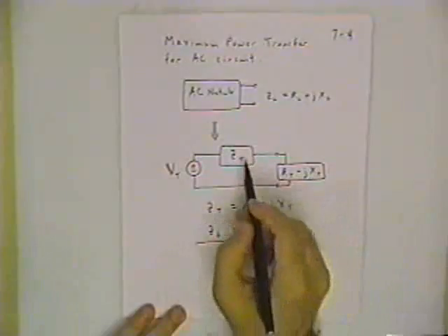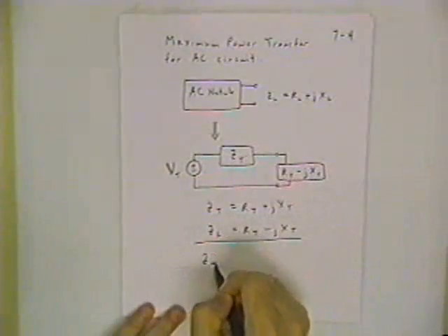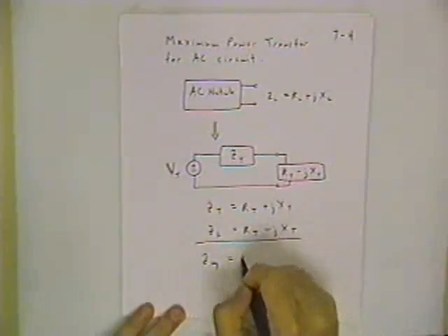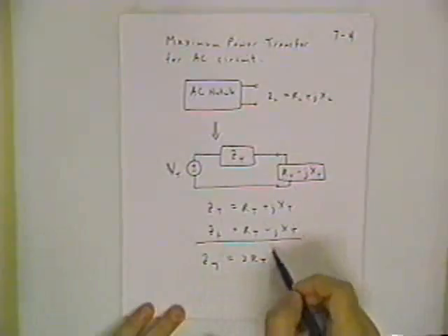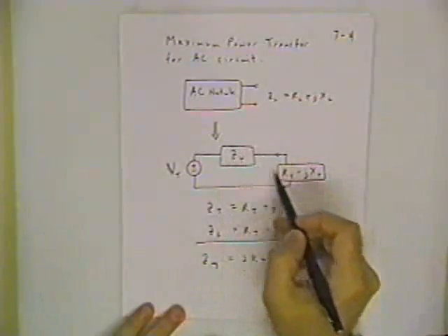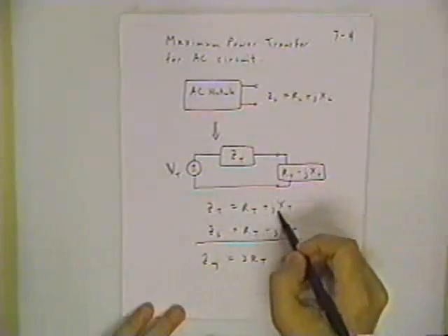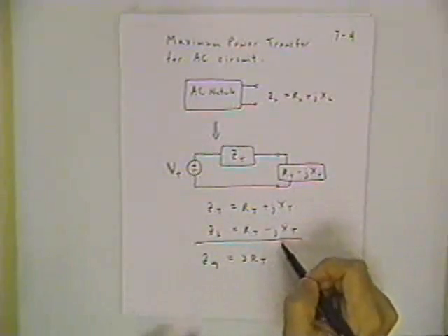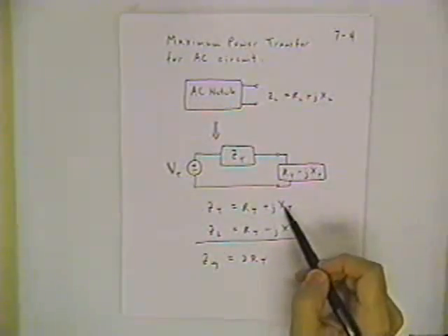And you notice what happens. These series connected impedances add together, Z equivalent gives you just a pure resistive load, equivalent load, if you include the Thevenin impedance and the load impedance together. The imaginary parts cancel out. And we're going to see in just a minute, the imaginary parts represent power that's trapped within the components.